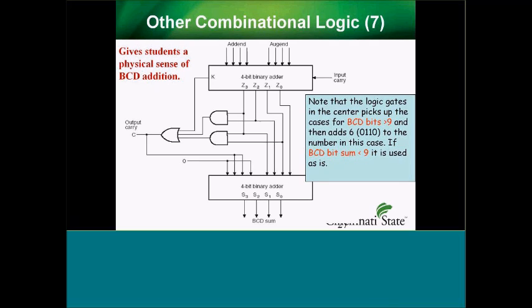Also, there's another thing that is important here. And that is that if you look at where these ANDs and this OR, this is just to determine if the sum coming out is bigger than 10. This is an important concept in digital logic, known as truncation. And so a lot of times later in other courses, which is Digital 2, if you're building linked counter systems using counter chips, a lot of times if you use a binary or a decimal counter, you'll have to truncate on a particular number and start it over. So you have to actually do something exactly like this.